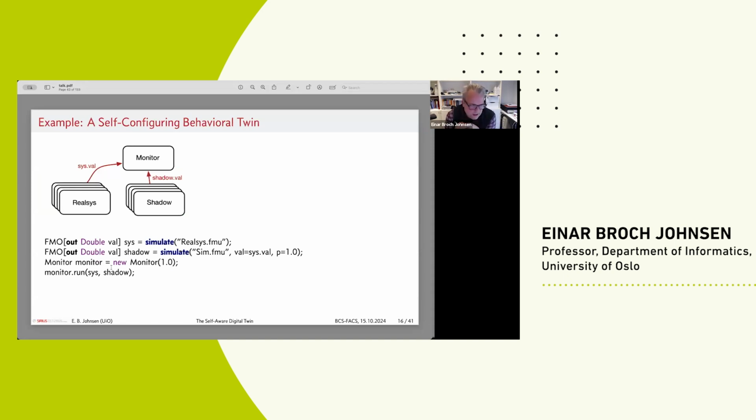So now we have this system where we have these shadow objects that are simulating behavior in the different rooms. They are connecting to each other, exchanging values. And then we have the real house where we can use the same kind of objects to embed sensor data, for example, temperature readings from the different rooms. And now we are interested in whether the shadow system can control this or can replicate the temperature development in the rooms. And this we can simply now do by connecting the values that we are reading from the smart house with the values that we are reading from the simulator, and we can monitor the difference between these.